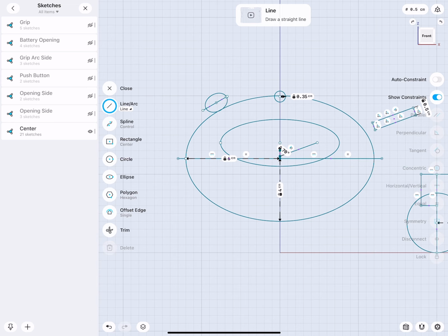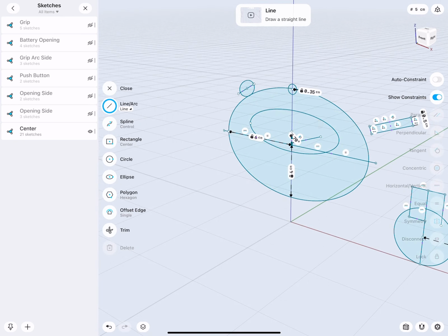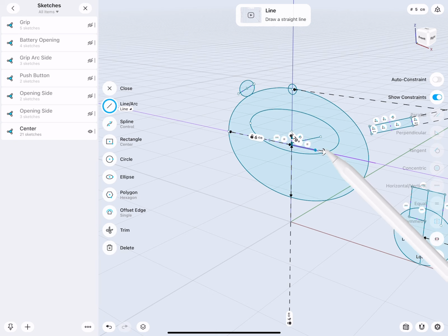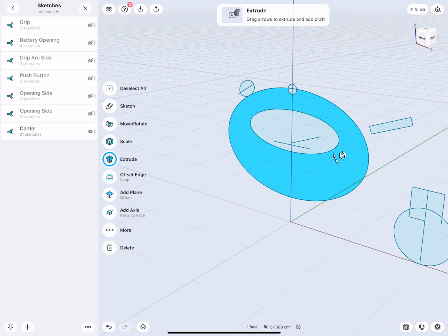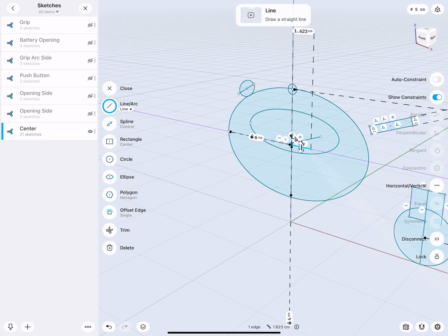The main reason why I set this one up is simply to very easily be able to open and close profiles. So for the revolve command, let me move this back. I do not want to select the whole ellipse. I only want to select half of the ellipse.